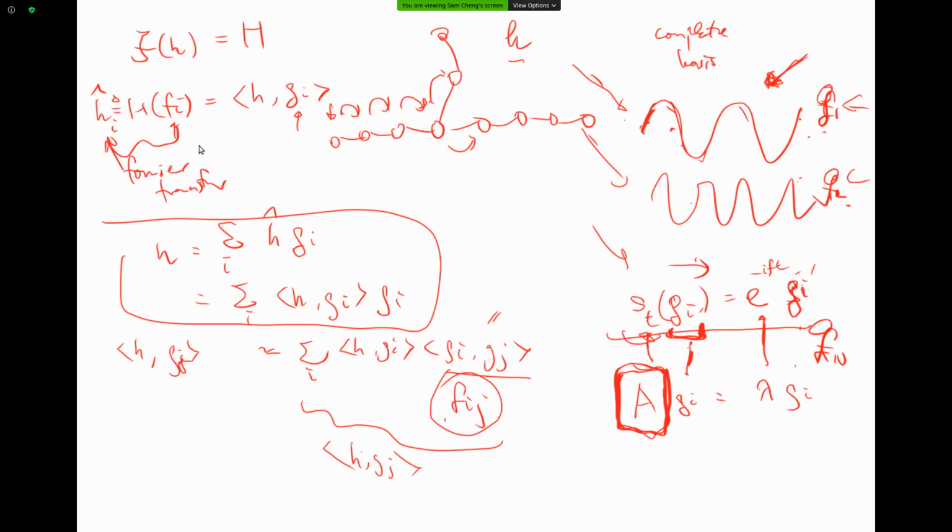What I mean is that we think of an ordinary 1D signal as a path graph here, and you can think of a discrete-time 1D signal as just a path graph, and then the shift operation, when I shift by one unit, is, for example, let me give a concrete example. Let's say I have 5 nodes here, which I call 1, 2, 3, 4, 5. If I shift it, first it starts from here and then it moves to here. If I start with a signal like that, the next time instant I should have 0, 1, 0, 0, 0, right?